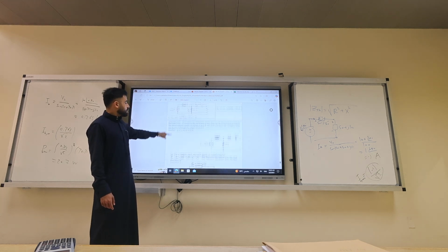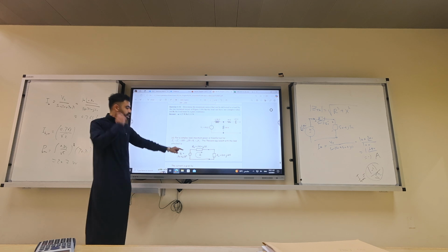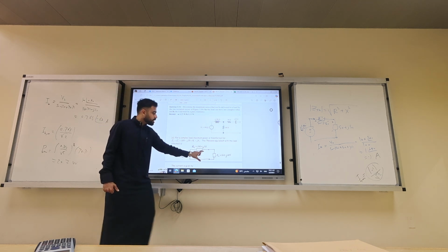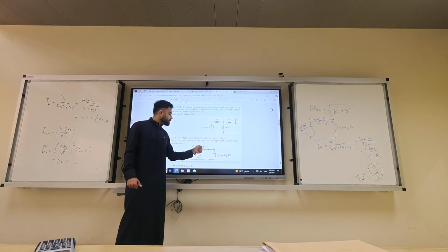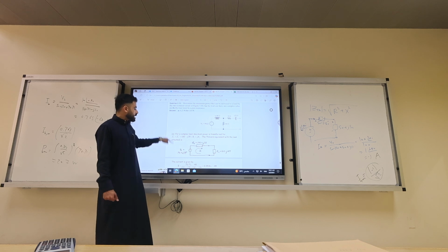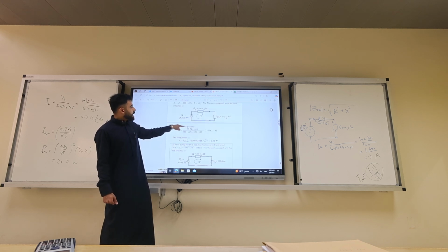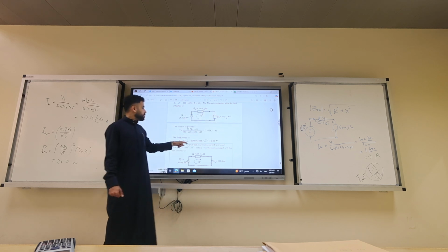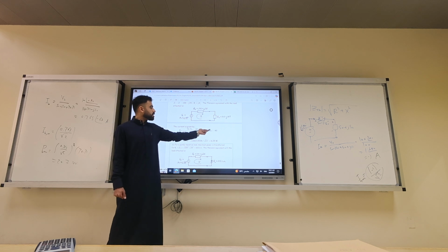It is solved here. To calculate the maximum power, you can see from the circuit, V Thévenin over R Thévenin, you connect to it 100 minus J25. Then you calculate the current. What's the current? 70.7 angle minus 45 over 100. Basically, they will cancel, which is going to be 0.3536 angle minus 45.